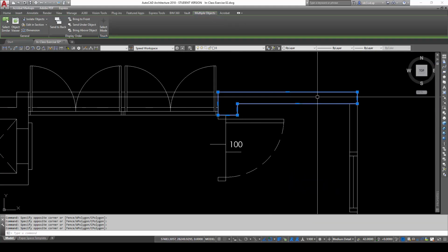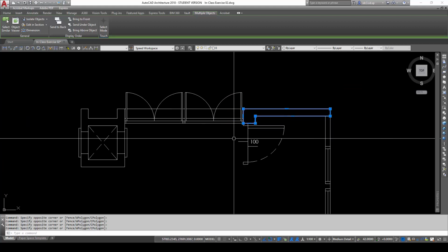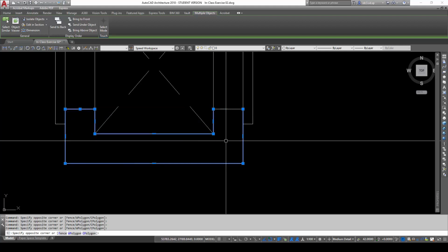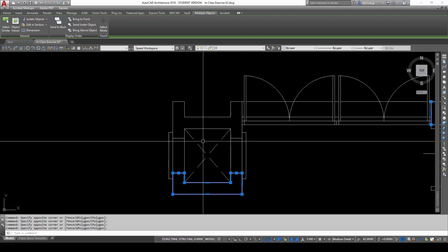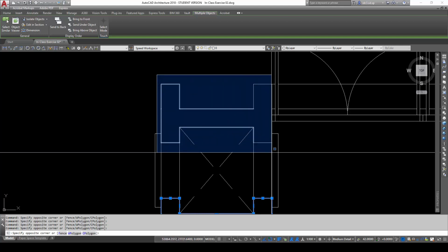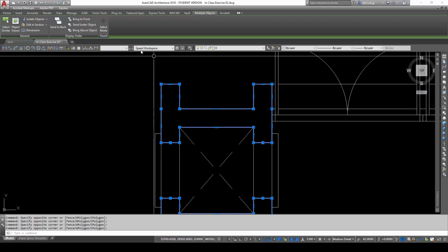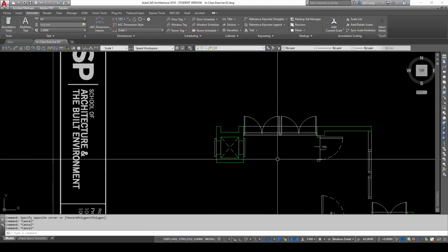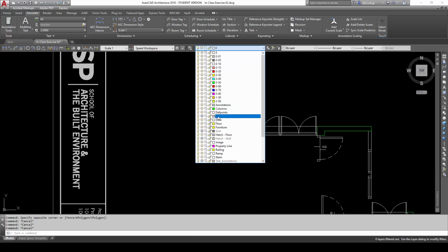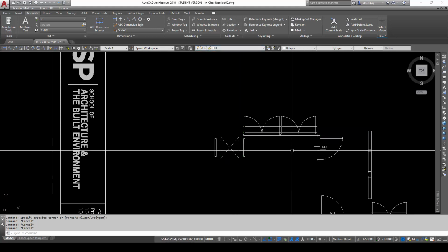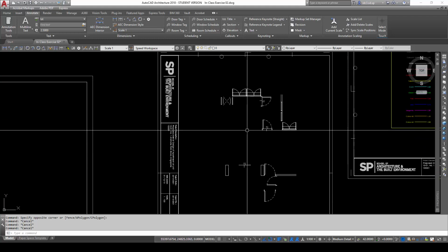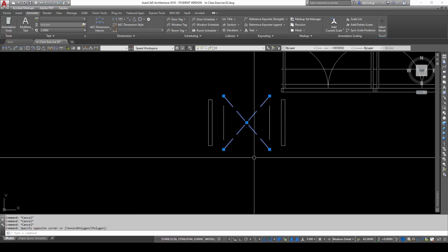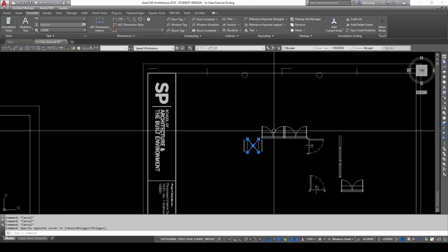All right, these are the reinforced concrete areas here. I'm just going to quickly select these areas and put them into the columns layer. Okay. And with these, I'm just going to freeze this layer as well. So if you notice, our work gets less and less and less. The more we complete, the less work there will be left in the drawing now.